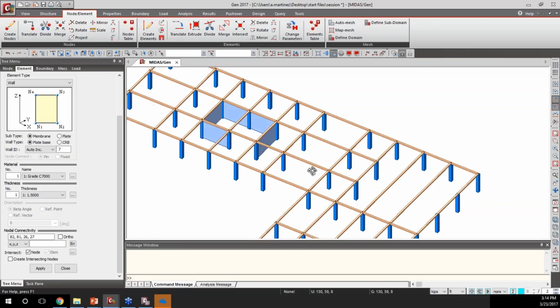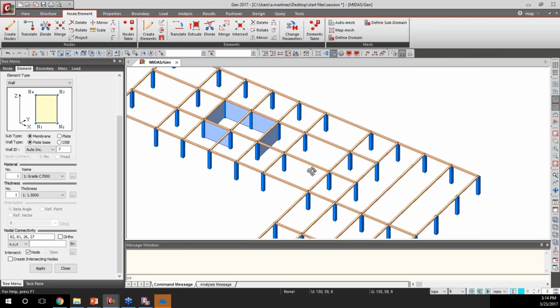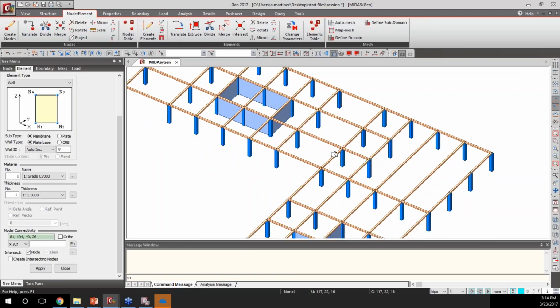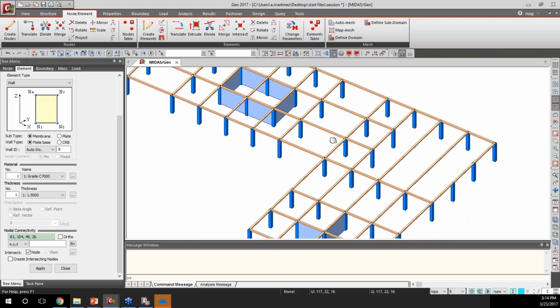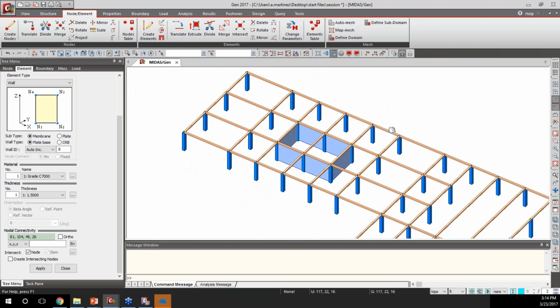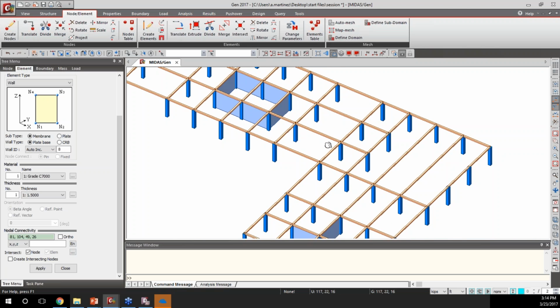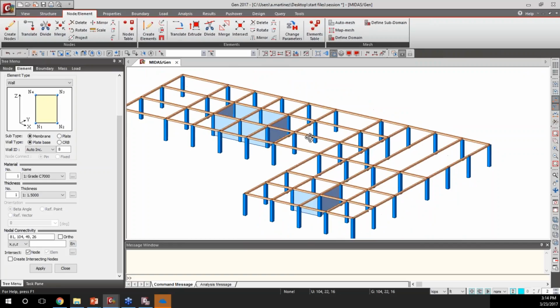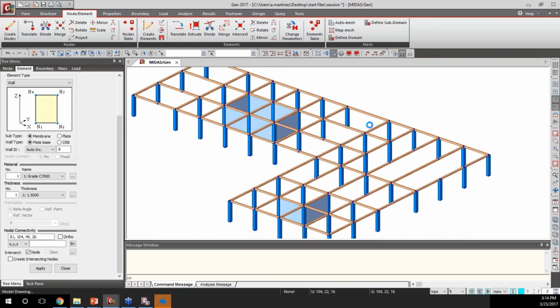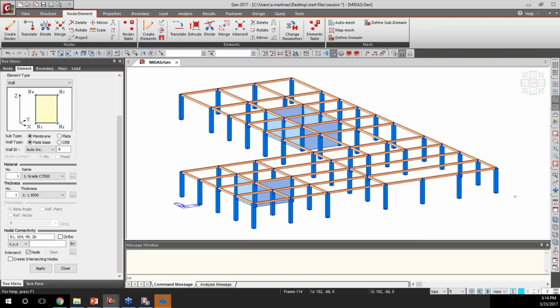If you want to rotate the model as such, you can hold down the scroller on the mouse and your control key on the keyboard, and it allows you to rotate the model. If you don't hold down control, but just hold down the scroll button on your mouse, it moves around in the fixed rotation. So if you want to rotate, just include the control command as well on your keyboard, or you can do either by manually activating it here. It's either a pan dynamic or a rotate dynamic. Or you can see all your views over here.